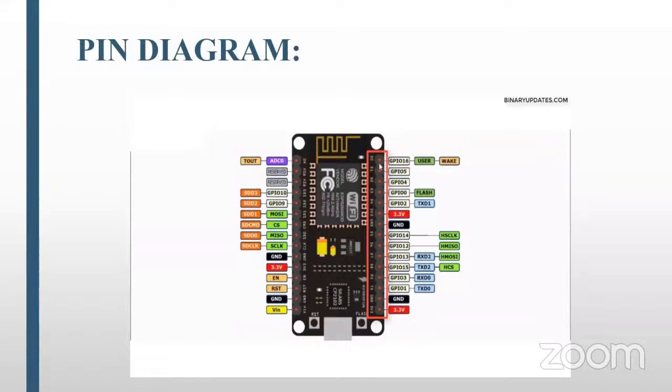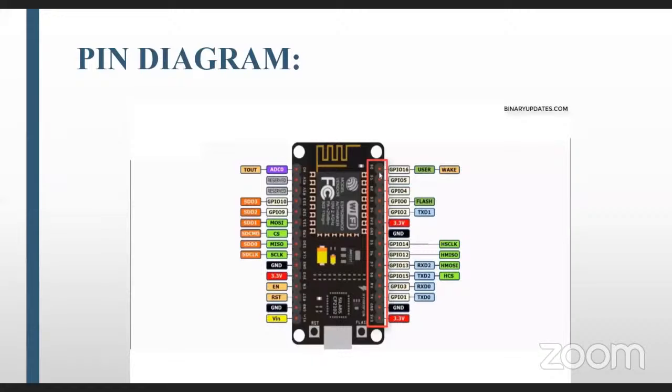But how do we define the analog value? As I already told you, this microcontroller gives one ADC. But what is that value? This microcontroller has a 10-bit ADC, built in. What is the most value and what is the least value? For an n-bit ADC we use one formula, 2 power n. This formula is used to define the values for the analog to digital converter.